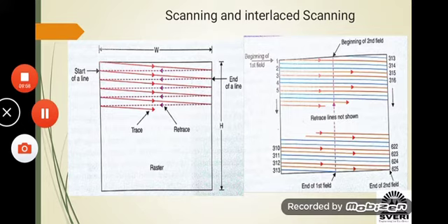Now how to capture those millions of pixels in the form of one signal? If we go by one signal for every pixel, there will be a huge number of different signals, which causes a huge amount of bandwidth. Also we need to use a very high-rate processor, which is practically very difficult, and that is why we go for scanning.